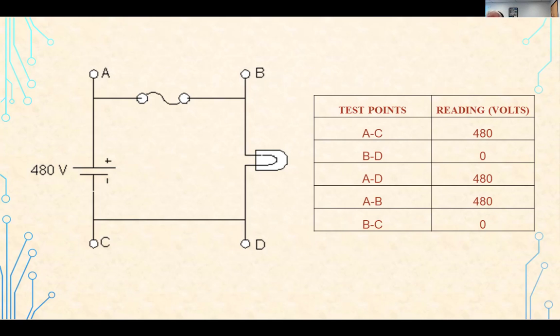If the fuse is good, then that should read 0 because the voltage is the difference across 2 points. So those would be electrically common. But the fact that A to B is different, that it's 480 volts, shows you that voltage isn't flowing through that fuse. Current's not flowing, and there is voltage across A to B.